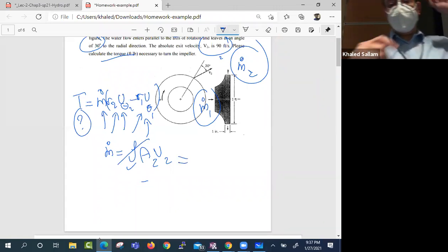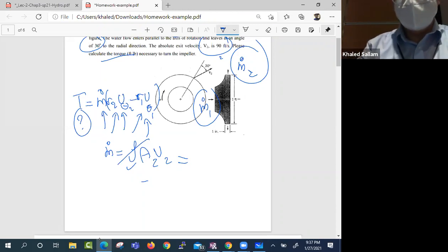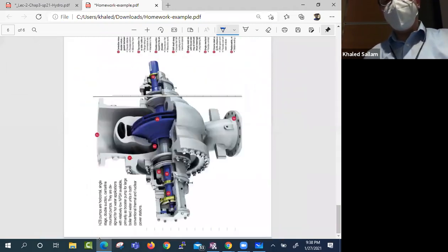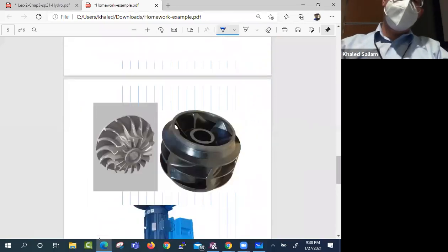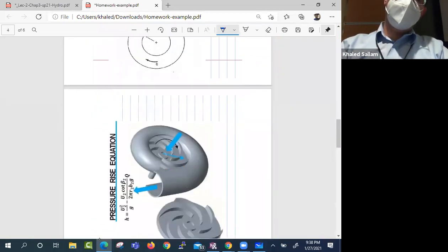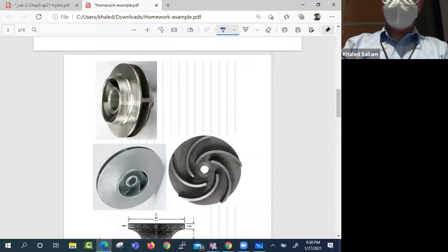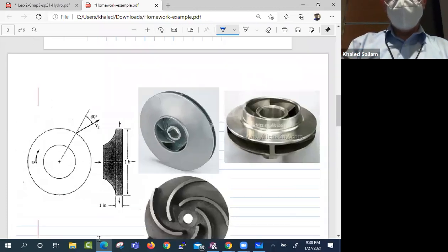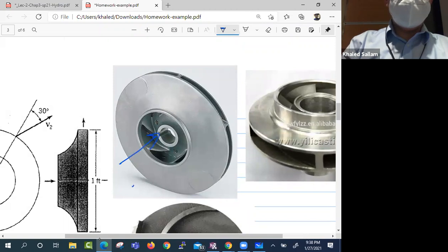So that impeller is opening like this, and then there is a strip on the outside that the flow leaves from. It's a cylinder, so it's 2 pi R2 H, where this is H. Okay, and if I step here a few slides, that's how it will look. Let me rotate. So look at this. This is area 1 V1, and then when it leaves like this.